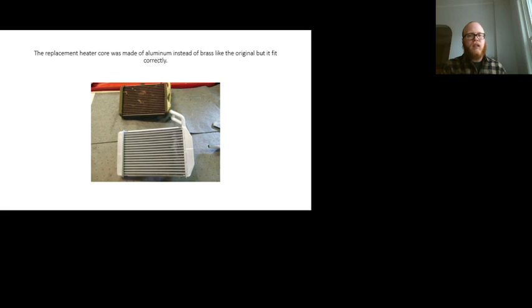While you're in there, because you had to pull the whole dashboard out, it's not uncommon to sell an evaporator at the same time as a preventative measure. You can see on this evaporator where there are these dark spots that might denote that some refrigerant was leaking due to corrosion. The refrigerant pulls an oil through the system with it, and so these oily spots are telltale signs that there's been a leak in those spots. Probably a very, very small one, but a leak nonetheless.